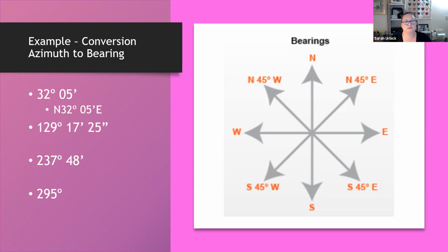My bit of advice while you're crunching those numbers on your calculators and converting that into something we can subtract from 180: anytime you're dealing with a problem like this, and you'll see it throughout the rest of the evening, my recommendation is to start converting into decimals. Get rid of the minutes and seconds, make sure you've got those conversions correct, and start dealing with decimals. Much easier than trying to add and subtract seconds, then minutes, and then degrees.